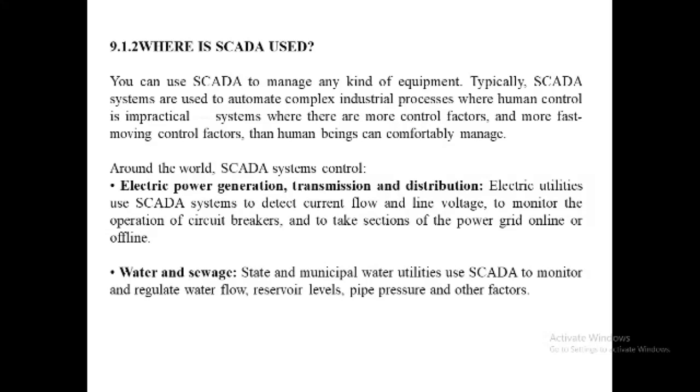These are larger computer consoles that serve as the central processor for the SCADA system. The master unit provides a human interface to the system and automatically regulates the managed system in response to sensor input. Fourth, the communication network that connects the SCADA master unit to the RTUs in the field.